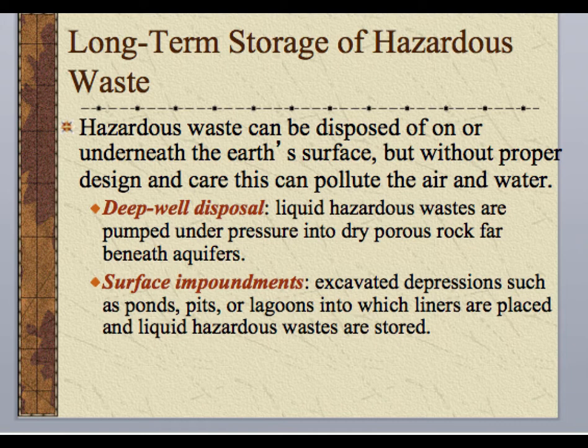Hazardous waste can be disposed of by deep well disposal. Liquid hazardous wastes are pumped under pressure into dry, porous rock far beneath the surface. And you also have impoundments, where you have depressions such as ponds or pits or lagoons into which liners are placed and liquid hazardous wastes are stored.